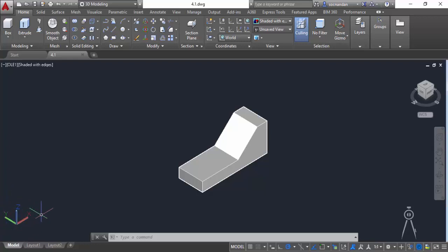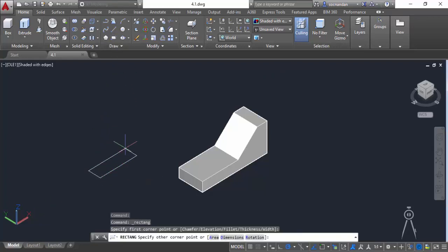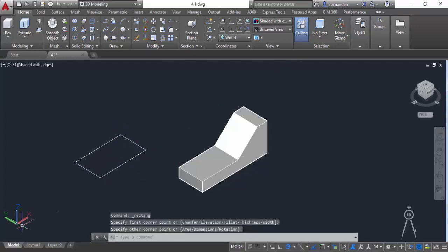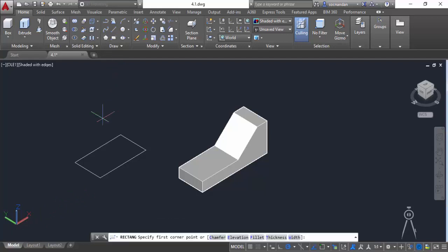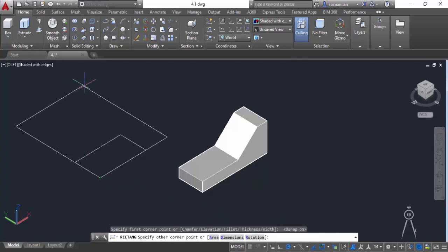System. Now, let's say that we want to create a new drawing. For that, let's start with draw command and let's try to make it. You'll now notice that I am only able to make this drawing on the XY plane. Now, even if I try to make my drawing on a vertical plane, so let's start from the same point. I'm going to turn on this object snap in order to snap it exactly at a point. And now, even when I try to move my cursor upwards, it's still snapping to this XY plane. So no matter how hard I try, it will always make your drawing on the XY plane.